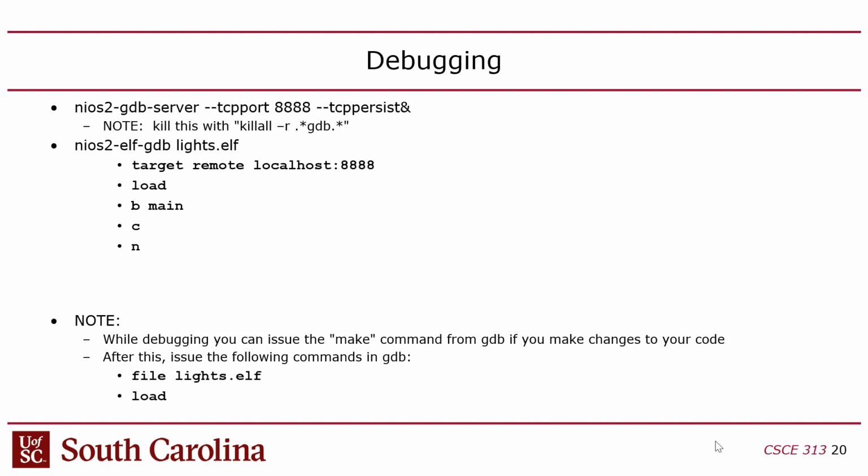And then you type load to load the program. You can set a breakpoint on main and hit continue, for instance. Load, by the way, resets everything. It loads the ELF file and gets it ready to run. You guys with me? And then you can just use GDB. It's nice, but the only problem is it doesn't support hardware watchpoints and it doesn't support the terminal user interface of GDB, if any of you use that. It's all text. Okay, any other questions about that?